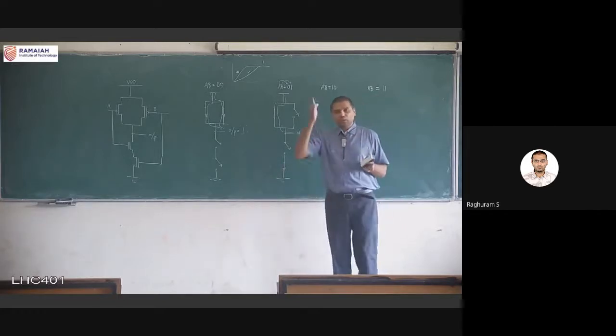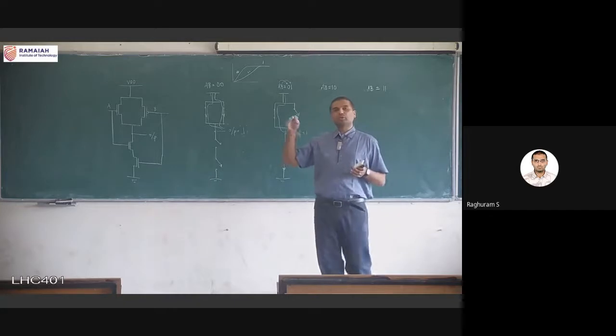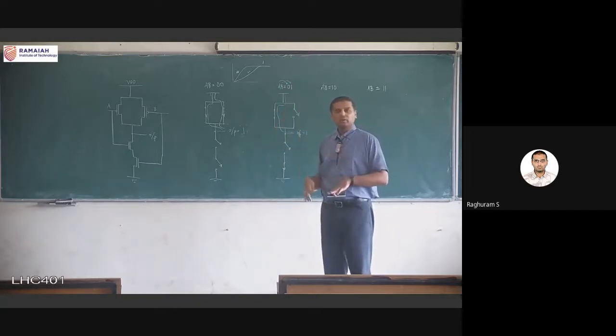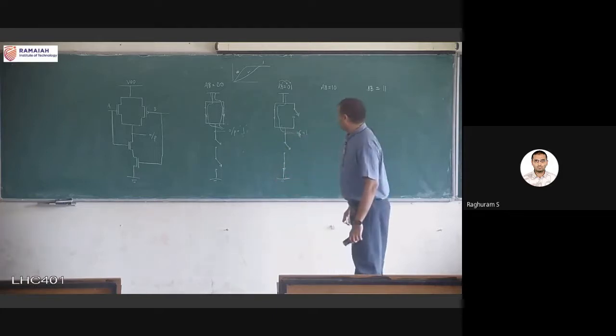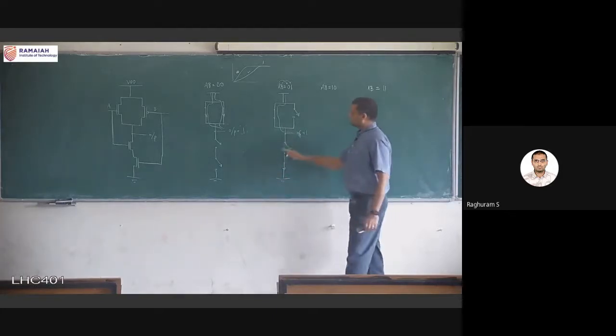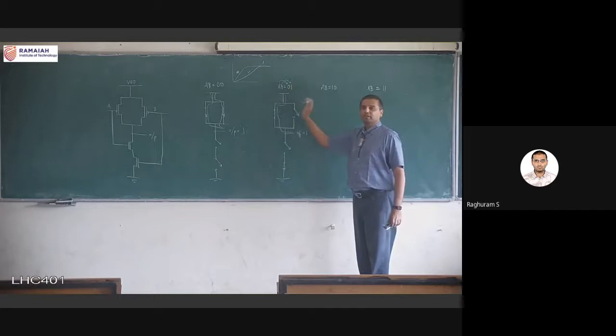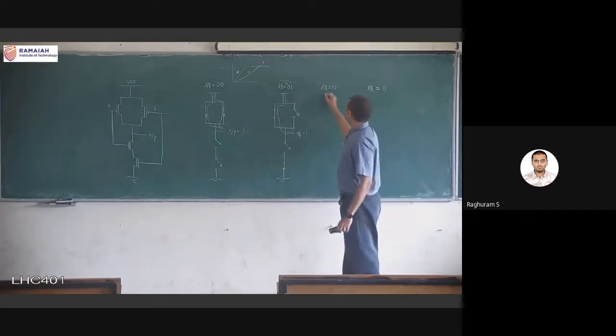Even if there is one branch through which the output is connected to VDD, or maybe later as we will see to ground, the level of the output reaches the perfect value of VDD. There is no voltage division or anything like that. Also below, since the first transistor itself is an open circuit, it cannot be connected to ground. It is only connected to VDD. This is the same as the previous case, only it is somewhat like a mirror image.